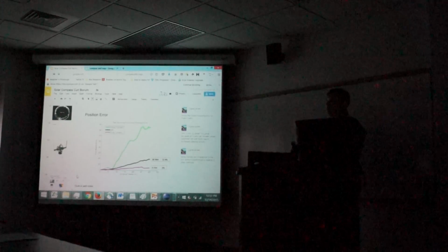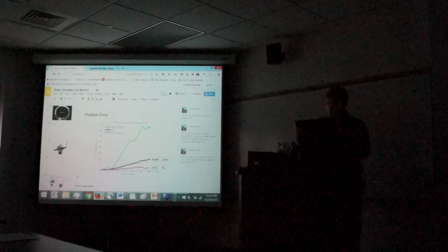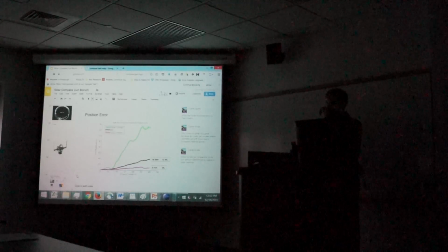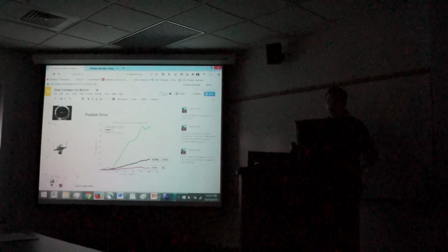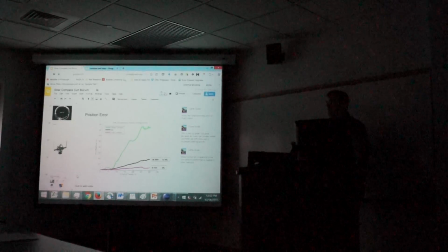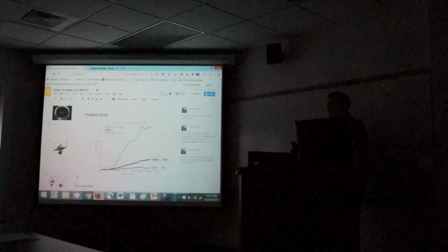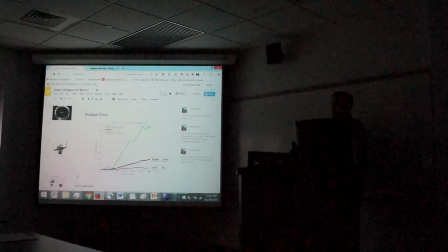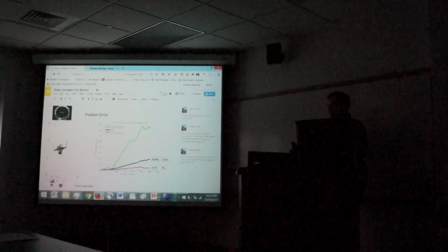And what was the frequency that you were recording? It was about 0.9 hertz, because it was 1.2 seconds between images on average for the sun sensor, and that was limited only because we were storing all the images. We could have run it faster and not stored all the images, but we wanted to be able to rerun the data set exactly as we did in the field test.